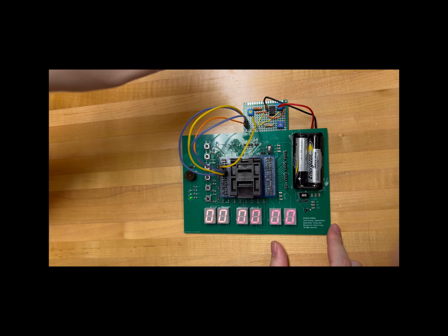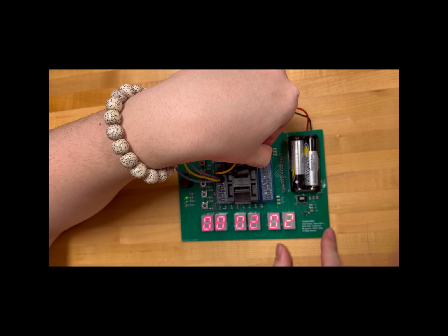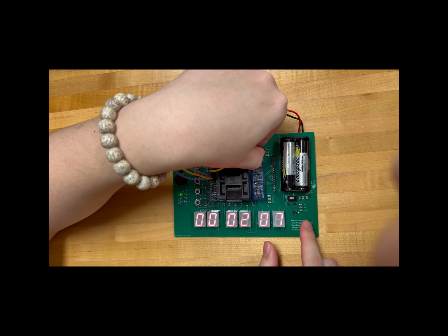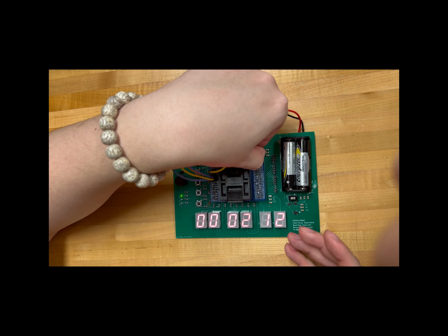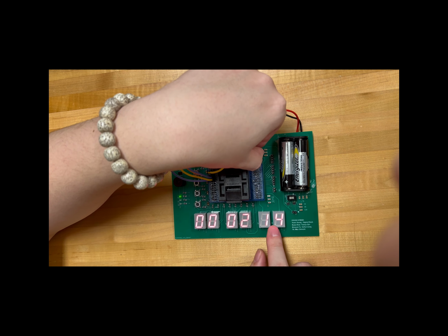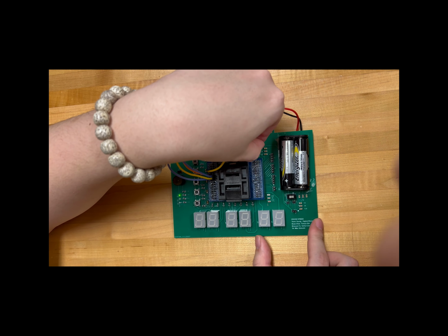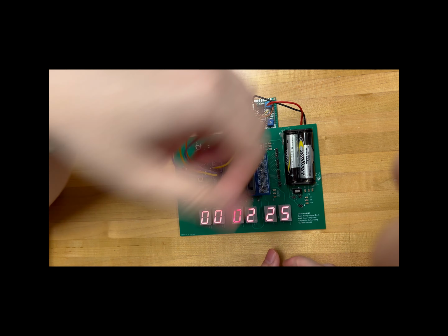We also designed a low power mode, because most of the power is consumed by the 7-segment LED. So here we have a switch that can disable the display, so it can save a lot of power, but this switch just disables the display, but the chip is still working. It means the time is still running. You can see right now it's 15 seconds, and we turn off the display, wait for a few seconds and turn on again. You can see the time is still running when I disable the display.